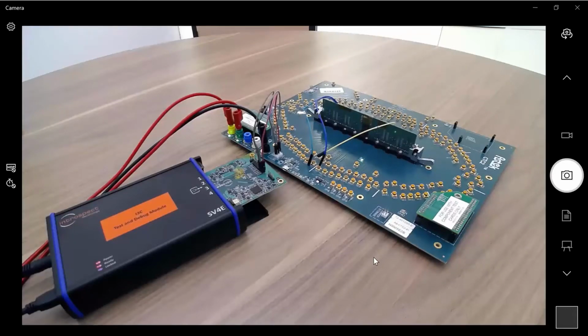Today we'll continue on sideband bus testing, and we will show how to perform complete characterization of sideband bus components on a JEDEC DDR5 DIMM. We'll show how to select the devices that we're testing and then create an automation test suite based on the Python programming language to allow you to characterize a device within only a few minutes.